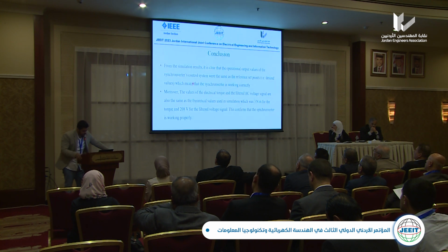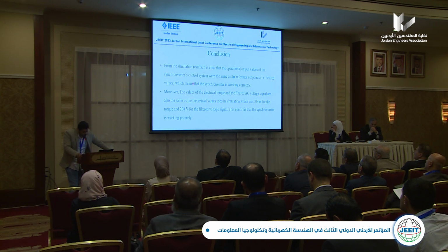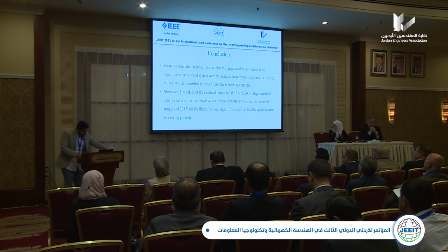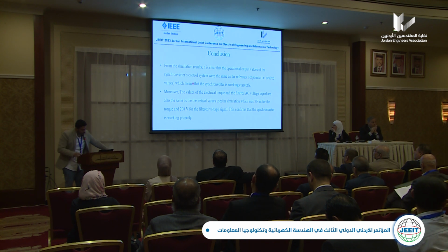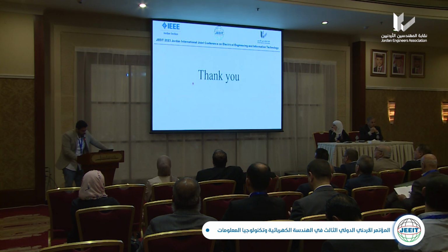And here is the conclusion. From the simulation results, it's clear that the operational output values of the synchronverter control system were the same as the reference set points, the desired values, which means that the synchronverter is working correctly. Moreover, the values of the electrical torque and the filtered AC voltage signal are also the same as the theoretical values used in the simulation, which were 3 Newton meter for the torque and 208 volt for the filtered voltage signal. This confirms that the synchronverter is working properly.